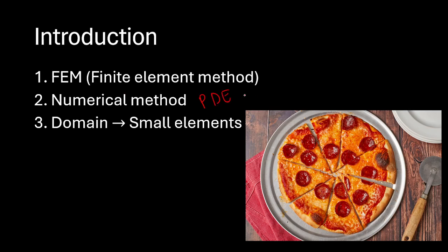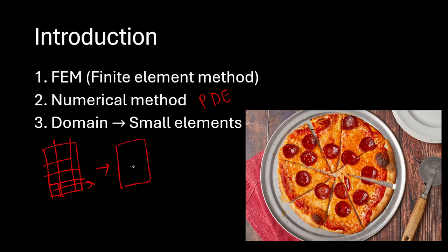The finite element method is a very powerful numerical method to solve complex and simple partial differential equations. In this method, the domain is divided into small pieces called elements. Each element's data is calculated, and later each element's data is assembled into global data and formed into numerical linear equations. The solution of the linear equations gives the solution of the partial differential equation.